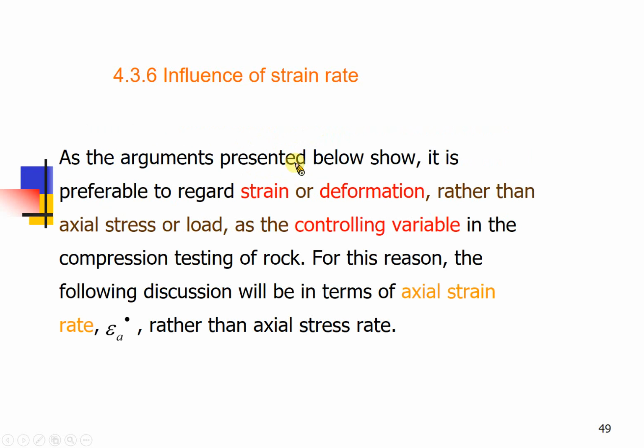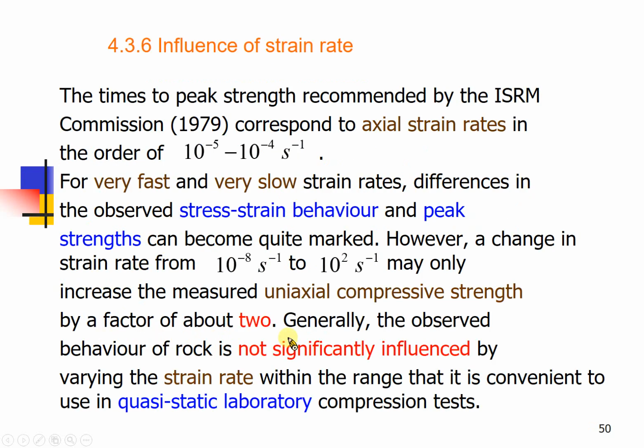Some people suggest considering the loading rate in terms of the strain rate. It will be strain control, not load control. They consider the loading rate from the actual strain rate, rather than the stress rate like I showed you, 0.5 to 1 MPa per second. Using strain rate, it could be roughly on the order of 10^-5 to 10^-4 every second.